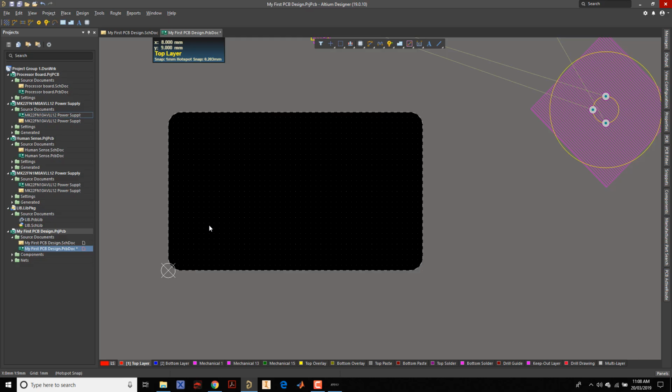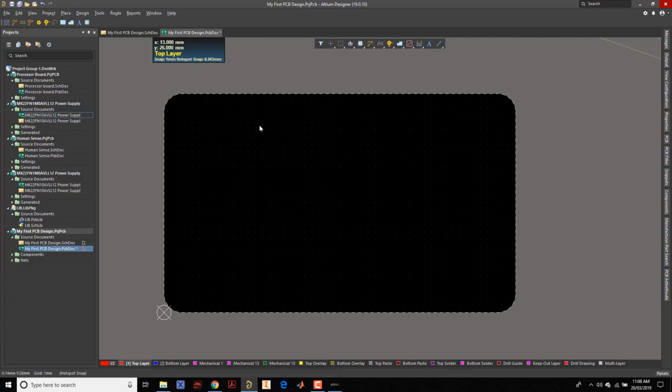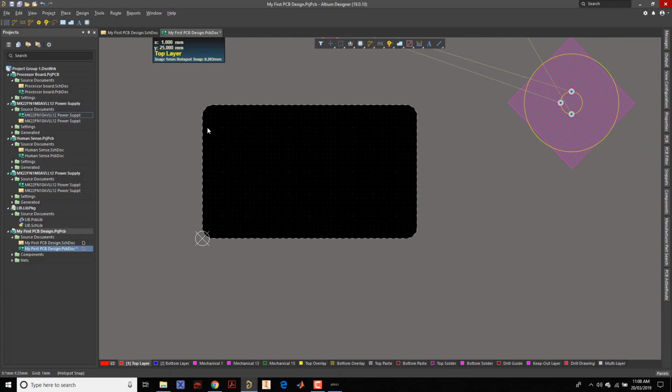They will add all their boards together and do it. And afterwards they will cut it. They will cut your board out for you. You don't want a situation where as they are cutting, they'll go and cut your trace or a circuit line. Okay. So there's something called a keep out area. You do it to tell them that all your circuits, the wirings, are within this area.